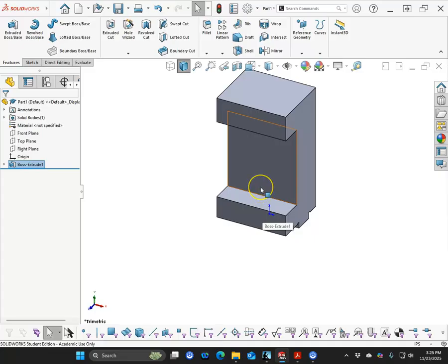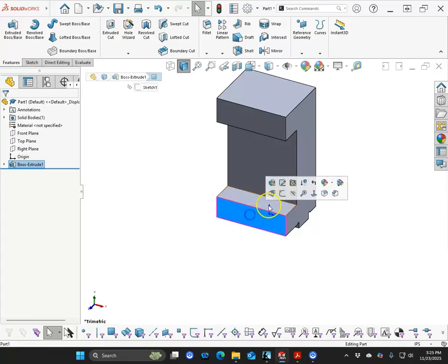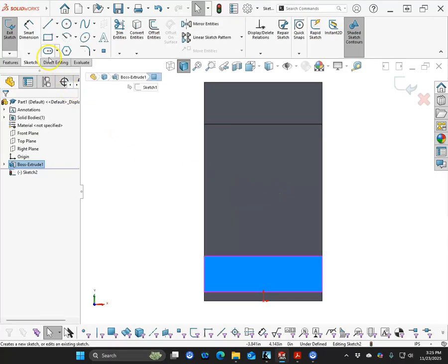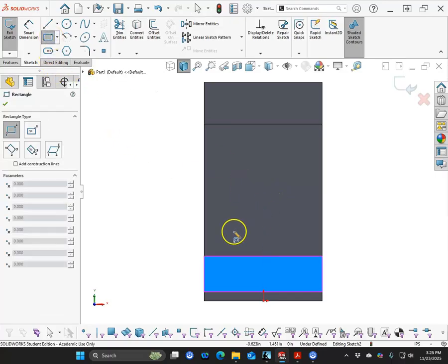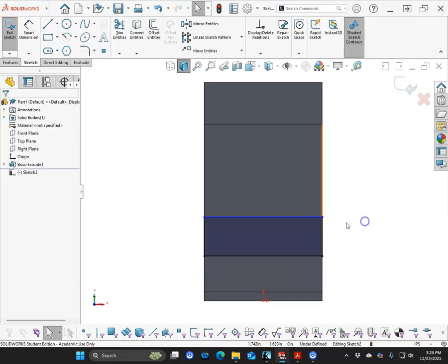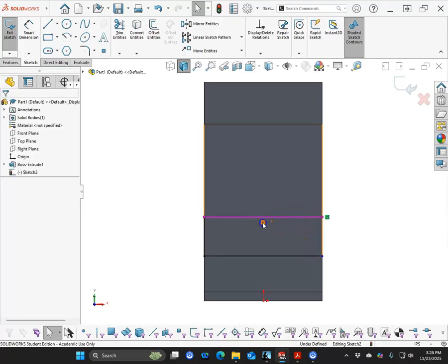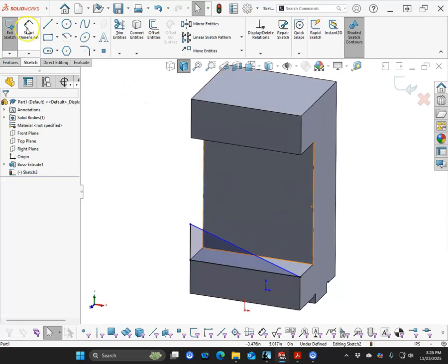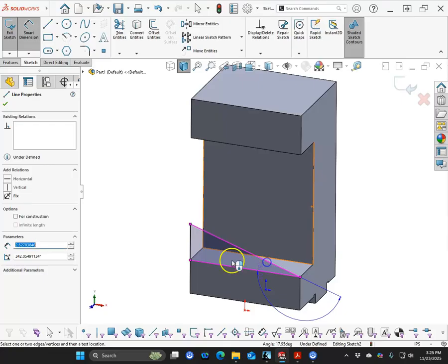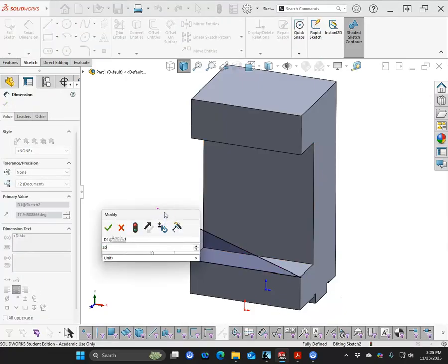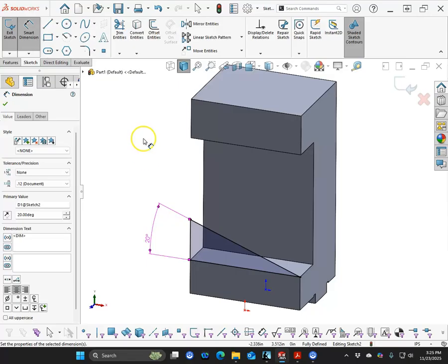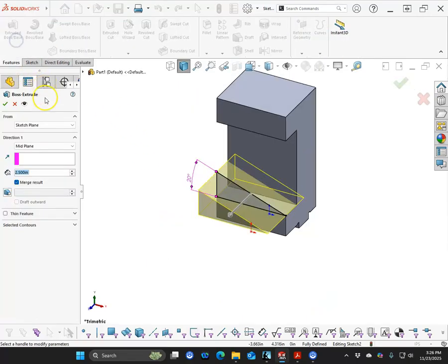All right, so it shouldn't really matter if we go from the front of the sketch. I'm going to use the rectangle. You can certainly draw for actually the 3, because that's going to come to a point. So that being the case, you could draw the 3 lines, but I like to make things complicated, so I will draw the rectangle, delete a line, delete a relation, and then generate my geometry.